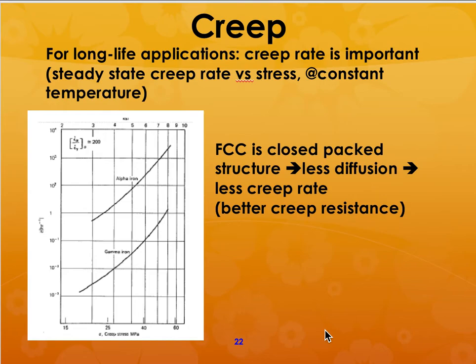So again, as I said to you, if you want the component to last for a very, very long time, then your creep rate is more important than your material. So if you want to look at creep, you plot the creep rate versus your stress level. From this again you can plot what is the safe stress level and what is the safe temperature level. From that you can determine what is good for your component, the usefulness of your component.